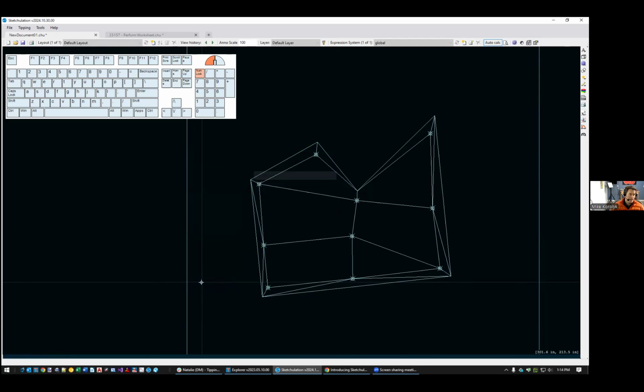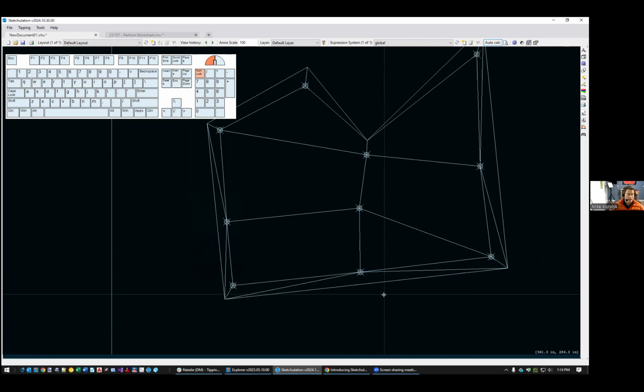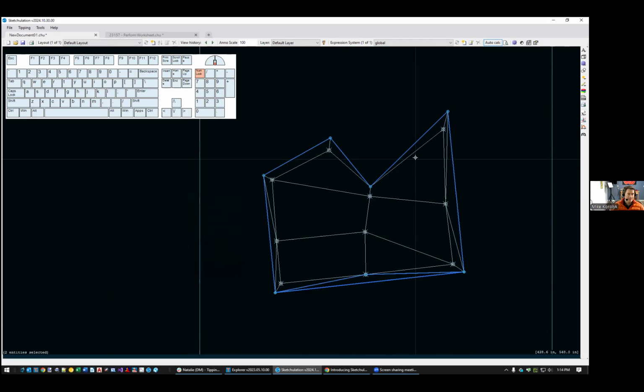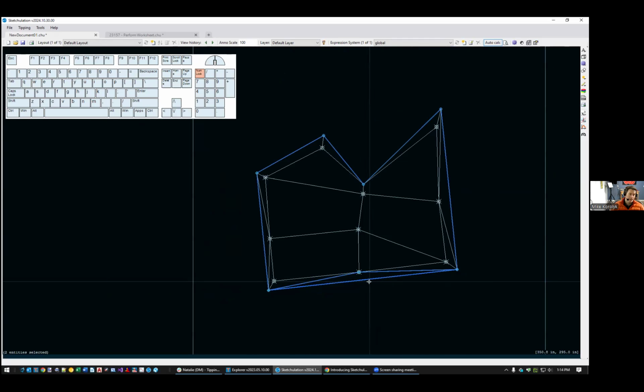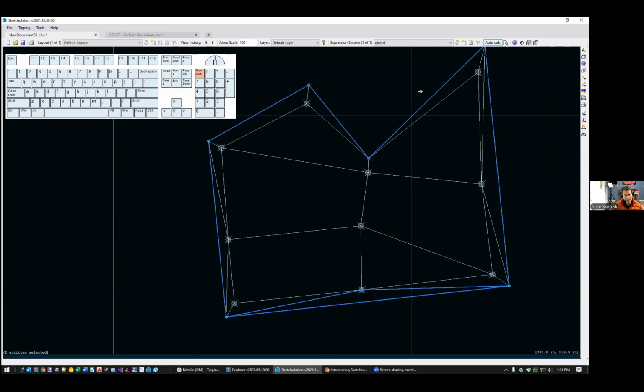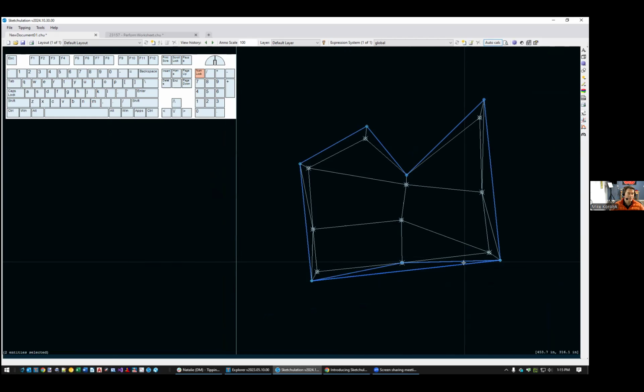But when I click OK, it creates a mesh of that outer shape. And the outer shape still exists. You see, when I selected the edge, I still have the outer shape, and I've selected one of these inner mesh entities. So what we want to do next is this trib mesh command, but you want to be careful that you don't grab the outer boundary. We only want to grab the mesh internal piece.